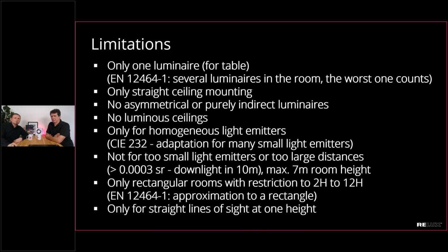And I guess there's one last point. Of course, the whole UGR thing only works for a straight line of sight of the observer. It's limited to this observer position. If the observer is looking above or downwards or changes the side angle, then it's not applicable anymore. And okay, this is really a hard limitation. So it's just valid for a certain situation.